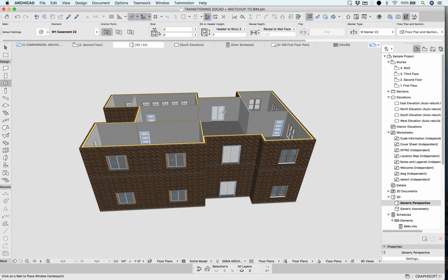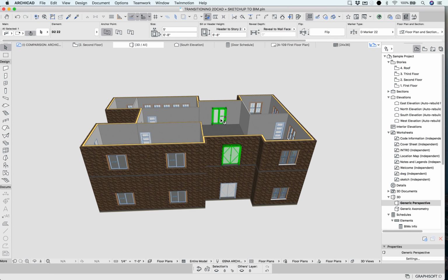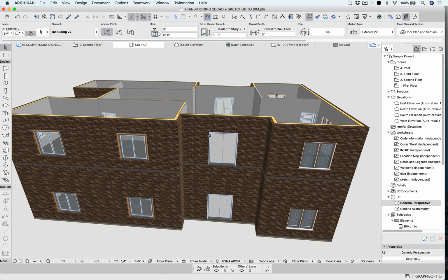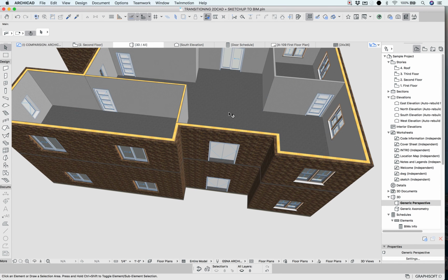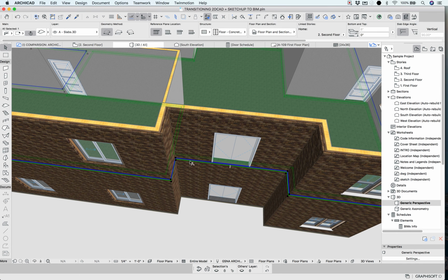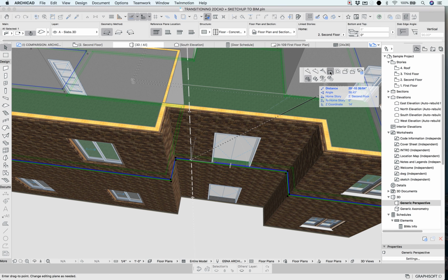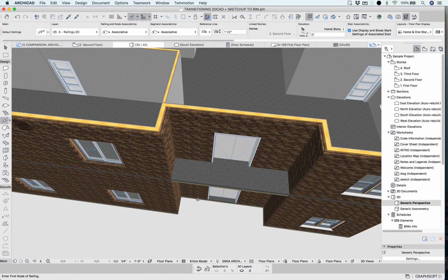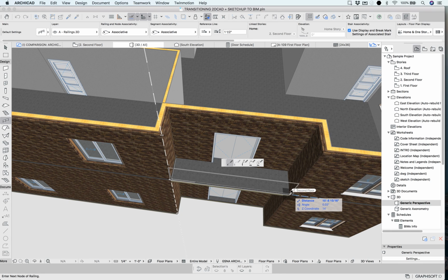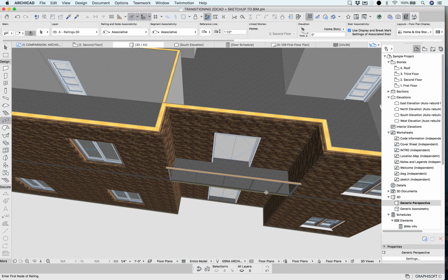So one, our doors are connected to our wall. So in these cases, I either want to build a balcony or get rid of that door. And just to show you what that looks like, if you are building a balcony, maybe it's selecting that slab in 3D and simply offsetting the edge. And then we have various other tools. We have our railing tool, and you can start to see how flexible we are.